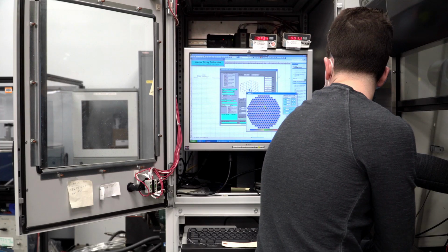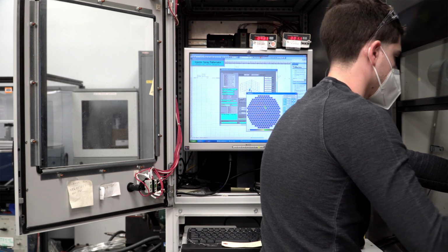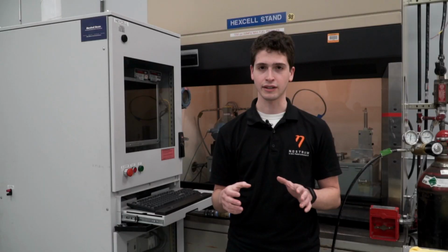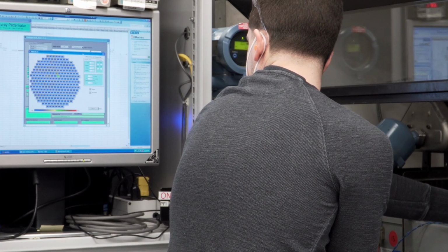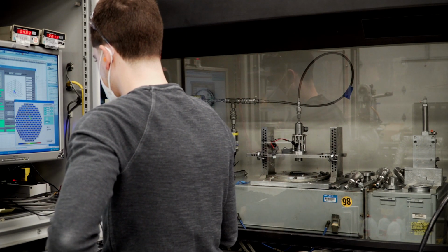With the liquid collected at each cell, the software then is capable to reconstruct the 2D representation of the pattern and calculates its geometrical information, but it's also capable to identify each plume and calculate the direction of each and also the percentage of mass in each plume.